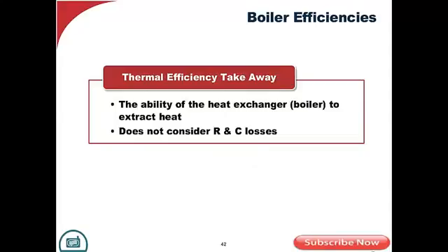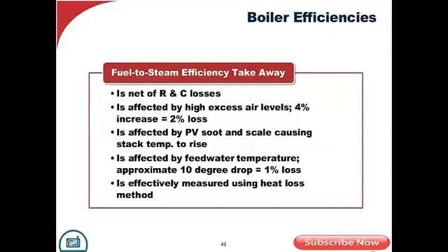Thermal efficiency, remember, it does not consider radiation and convection losses. So those BTUs are going into the room that's already 100 degrees. It's not going into the process, not going into the hot water to heat that building. All right? What you want to look at is fuel to steam efficiency or fuel to water efficiency. So those are your takeaways.